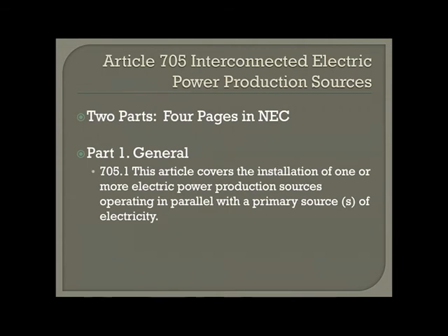So obviously, most of you guys know when a PV system works its best. Well, that happened to be that day that fire started. It was sunny out, it was snow on the ground, and it was cold. So that system was pumping out as much as it could, and it overloaded the breaker in the house, which might have been getting old. Could have had a loose connection. But personally, I think you should look at them diagrams more, and OneLine diagrams, and talk to us. See what we prefer, what LES prefers, and what's going to work for each system, okay?